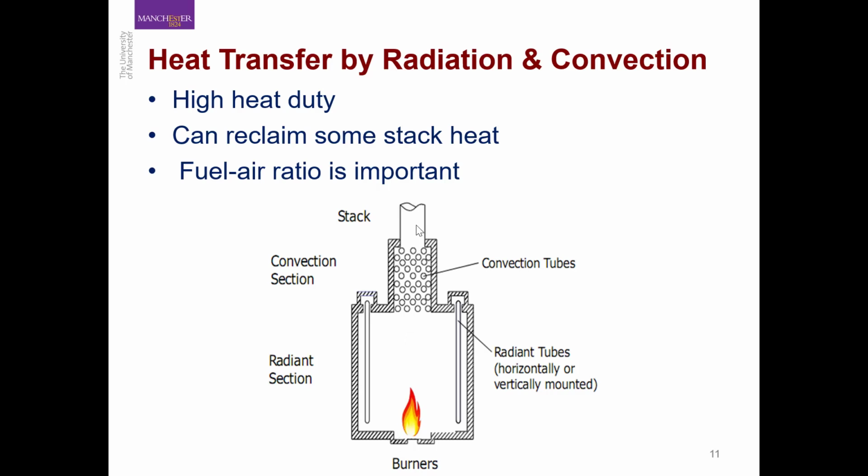These kind of furnaces are used when you need very high heat duty. Also, we can use these furnaces to reclaim some of the heat from the stack, and we will talk about it in the next parts of this lecture. For this kind of furnaces, fuel to air ratio is very important. And again, when we look at theoretical flame temperature, we will talk about fuel to air ratio there as well.